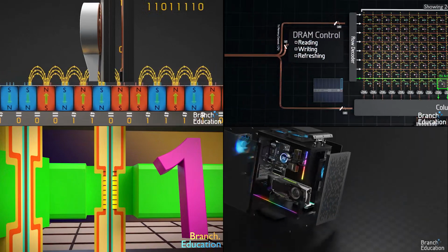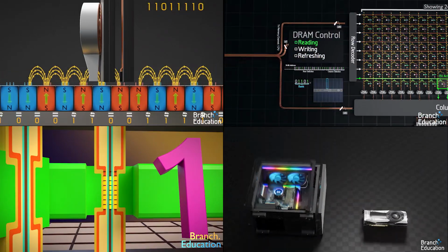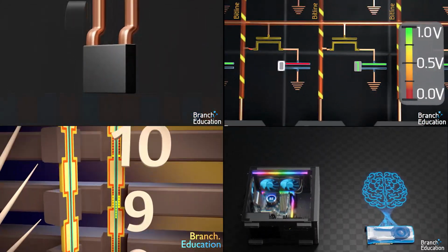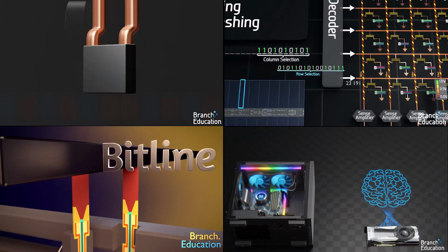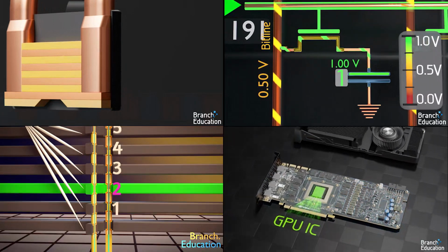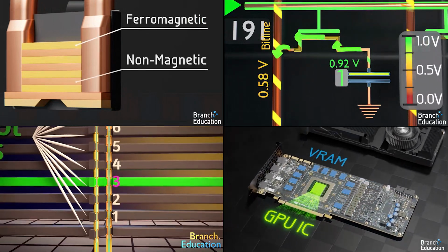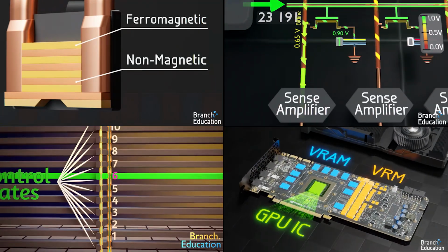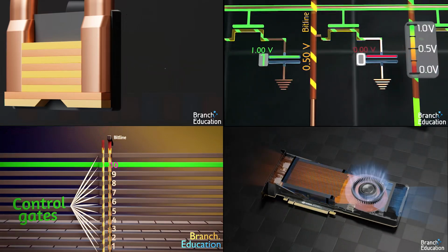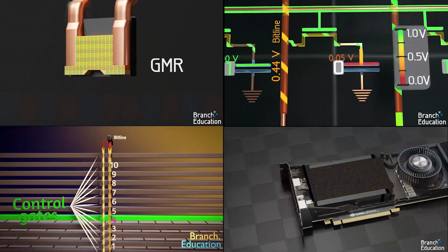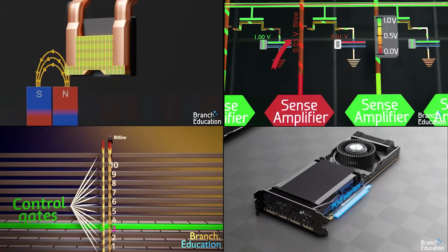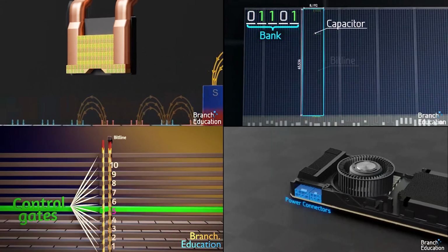Let's get back to dissecting this computer and move on to the graphics card and GPU, which is also the brain of the computer. Well, actually this analogy doesn't really work very well, but anyway. Opening the graphics card, we see another PCB with the GPU's integrated circuit in the center, VRAM chips all around, and the voltage regulator module on the side. Above the IC is a heatsink with a fan to dissipate heat, and on the side of the graphics card are HDMI and display ports, a PCIe interface, and then on the other side is the input power connector.